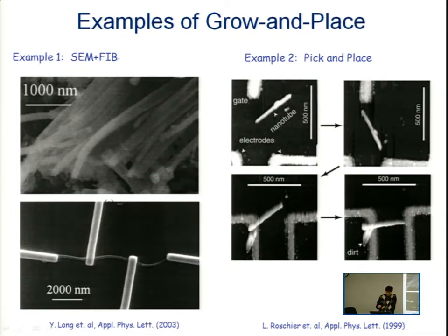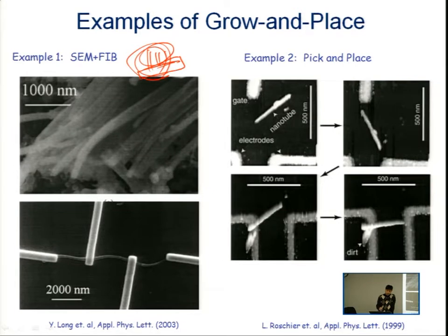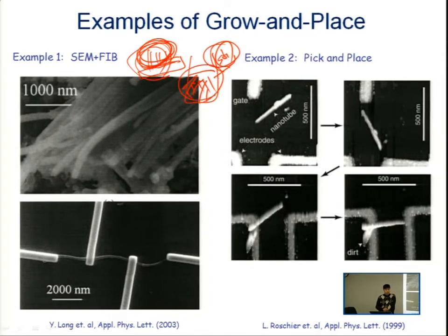One is, after growing those nanowires, people scratch the nanowire-grown substrate and harvest the grown nanowires, and then mix the nanowires with some kind of solution. Then people apply this mixture of nanowire solution onto a blank substrate by spin coating or whatever, and in some areas the nanowires are pretty isolated.